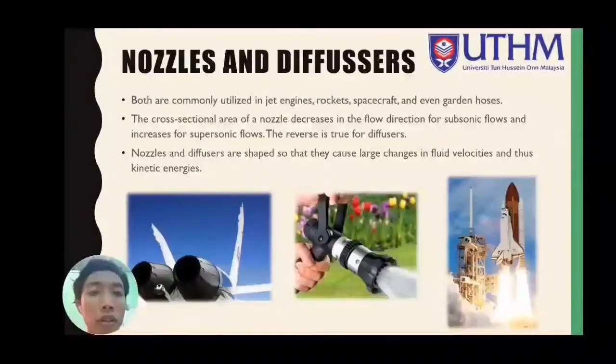The cross-sectional area of a nozzle decreases in the flow direction for subsonic flows and increases for supersonic flows. The reverse is true for diffusers. Nozzle and diffuser are shaped so that they cause less change in fluid velocities and thus kinetic energies.